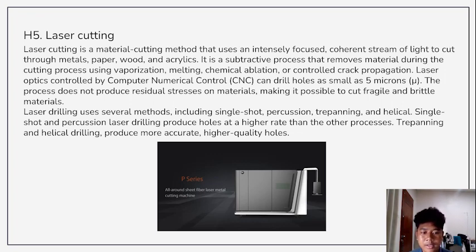Laser drilling uses several methods, including single shot, percussing, trepanning, and helical. Single shot and percussing laser drilling produce holes at a higher rate than the other processes. Trepanning and helical drilling produce more accurate, higher quality holes.